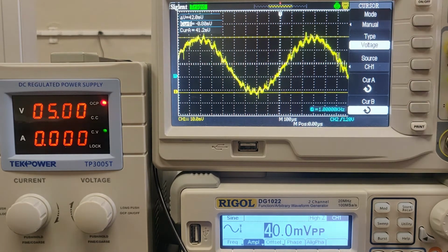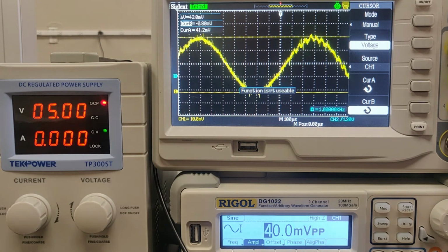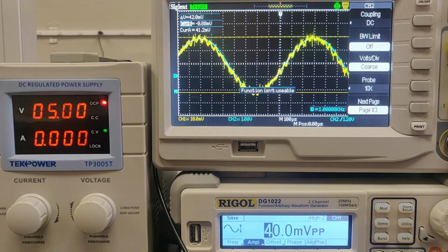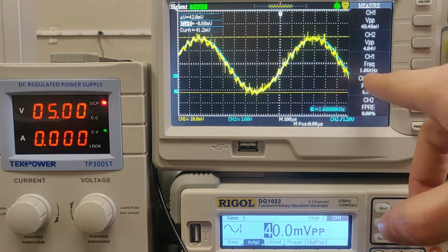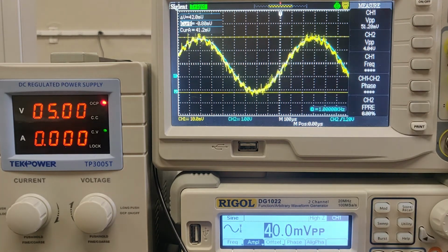With that, one thing that we can also do real quick, before we find the bandwidth, is find the phase shift. This is a non-inverting amplifying setup, so I'll give you a quick guess as to what we should see as our phase shift. And unsurprisingly, it's close to zero. It's bouncing around, and that's more so because of the noisiness at our low amplitude signals.